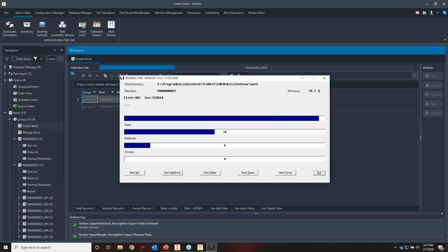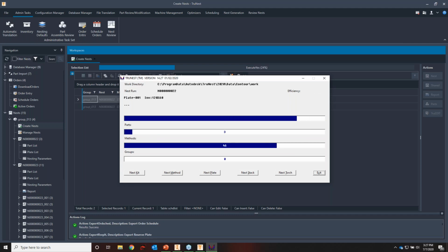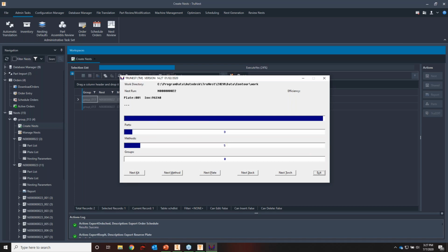So it's going to go through that same process. It's going to go through the nesting on each available piece of inventory, and it's going to optimize the position of the parts on the nest for what we call multi-torch logic. Even with the multi-torch logic turned on, it's going to optimize the parts on the plates in such a way that it still leverages all the sheet cutting as well as the reduced piercing logic that's being applied.